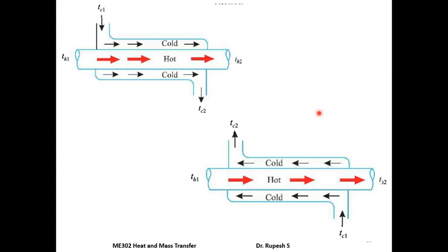Since LMTD is greater, your total heat transfer rate associated with the counterflow heat exchanger will be higher compared to that of parallel flow heat exchanger, provided mass flow rate and inlet temperature of the fluids are maintained constant. So in practical cases, we always prefer a counterflow heat exchanger to a parallel flow.